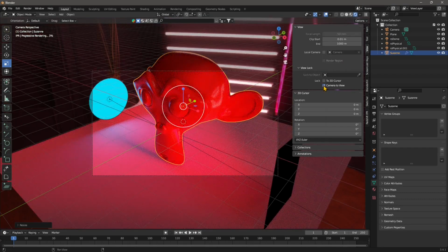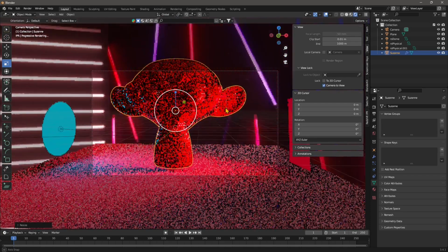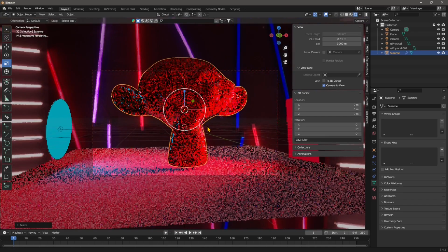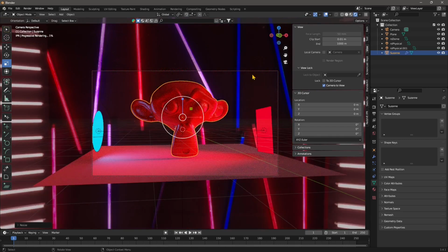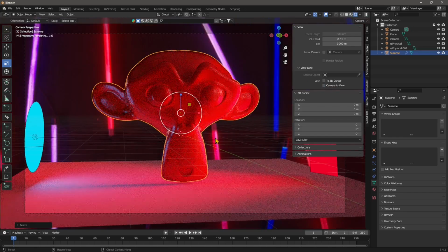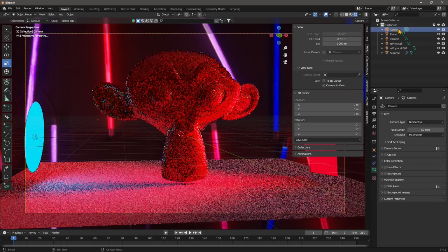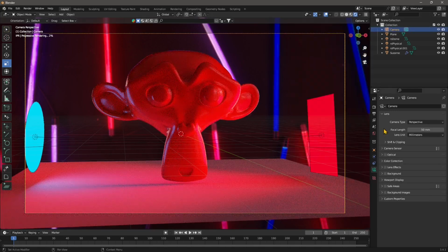Now what I'm gonna do, I'm gonna lock the camera. I'm gonna get in the camera. I'm gonna lock the camera to the view, and I'll choose another point of view. And then when I'm finished, I'm gonna unlock and then zoom in with the scroll wheel. And again, if you're having problems with all this stuff, just check the Blender playlist. So I'm gonna exit the camera or enter the camera when I want to go back in this view. So now that I created the camera, now I am inside the camera.